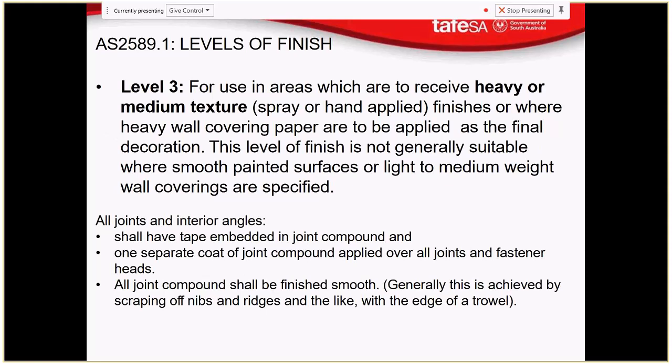Level 3, for use in areas which are to receive heavy or medium texture spray or hand applied finishes, or where heavy wall covering paper is to be applied as the final decoration. This level of finish is not generally suitable where smooth painted surfaces or light and medium weight wall coverings are specified. So the people installing the plasterboard, gyprockers, may be able to get away with a slightly lower quality of finishing if they know that it's going to have a textured coat over the top, or it's going to have wallpaper over the top, which is not particularly common.